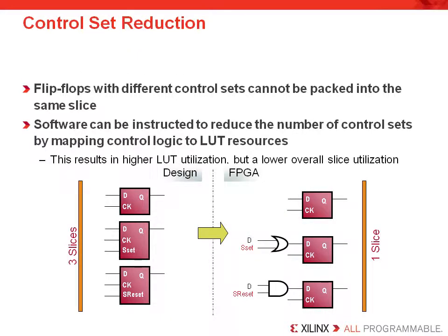And as I mentioned, flip-flops with different control sets cannot be packed into the same slice. So in this example, we see 3 flip-flops are synthesized to force some control signals to be associated with LUT inputs so that these registers can be packed into the same slice. Now this is done in XST by using the reduced control set synthesis option. It is not done by default. Hopefully it will eventually, but what is most important is that you code for synchronous reset and code for clock enable so that you can take advantage of this functionality in your FPGA. That is, that your synthesis tool can take advantage of it.